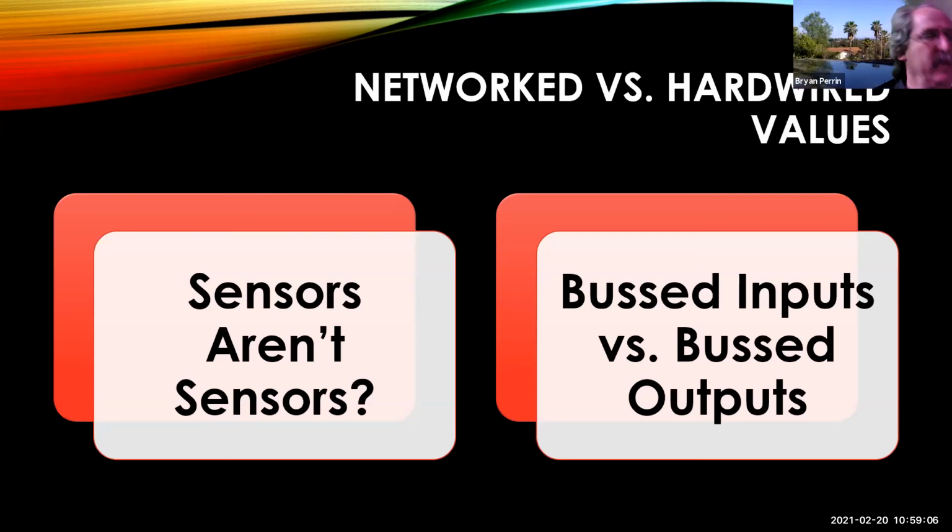And this gets really confusing because there are some systems out there where the bidirectional controls are in one module, but all the sensors report to a different module. So in other words, the module with the bidirectional control doesn't show you the PIDs for the parts that are measuring the movement of the bidirectional controls. Oh, that's strange. But yet they're moving. So how do you know if it's moving? I can turn it on, but I can't see the PIDs. If I see the PIDs, I can't turn it on, because it's two different modules.